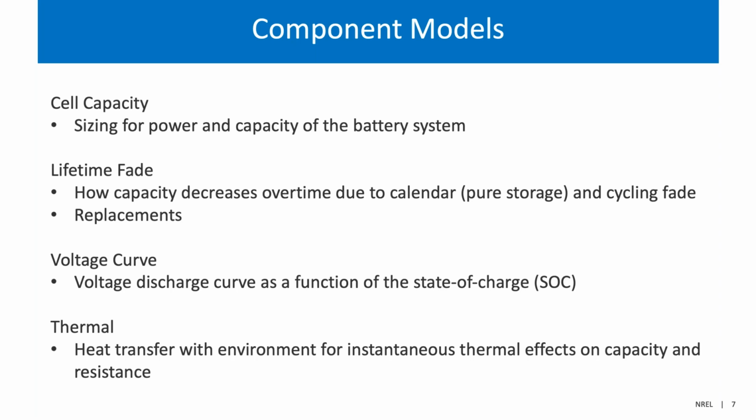The battery lifetime depends strongly on conditions under which the battery is operated, such as temperature, state of charge, total energy throughput, as well as the charge and discharge rates. While there is no universal battery lifetime model, studies often break up the fade mechanisms into calendar and cycling, which we follow in the lifetime model in SAM. The lifetime fade then affects the replacement of battery systems.